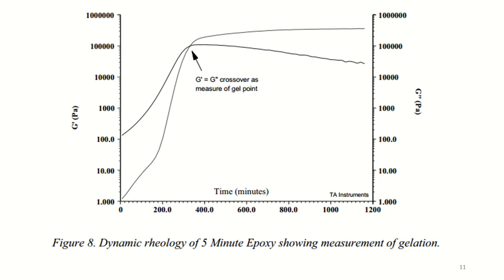Note that a rubbery plateau modulus between 10^5 and 10^6 Pascal is created, and it's reached after long times, demonstrating that vitrification that would result in a modulus greater than 1 GPa did not occur in this sample.